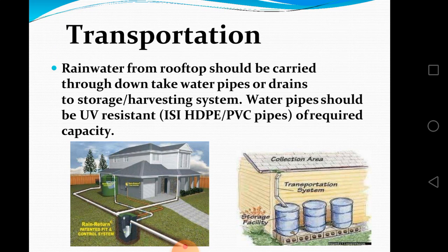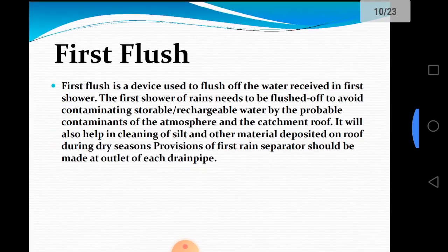The water should pass by gravity, and we should use UV resistant pipes of required capacity. PVC pipes are UV ultraviolet resistant, and HDPE pipes are also resistant pipes.